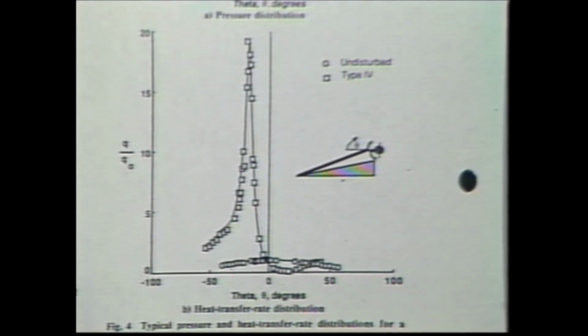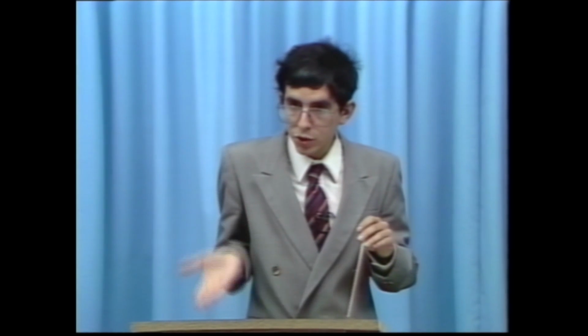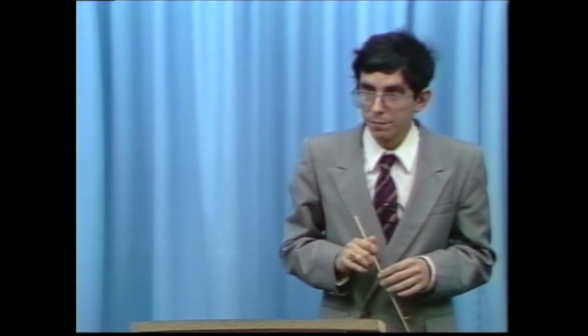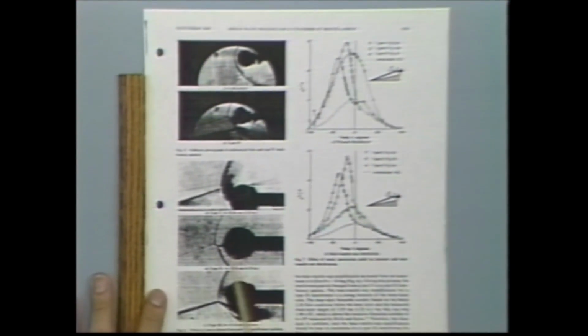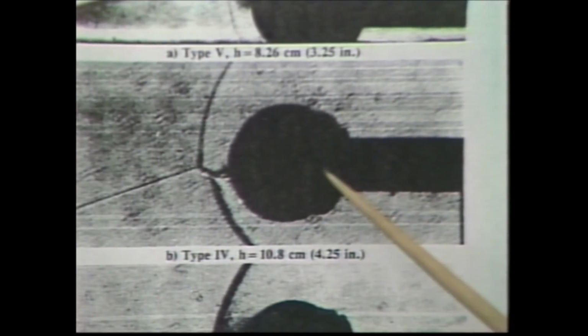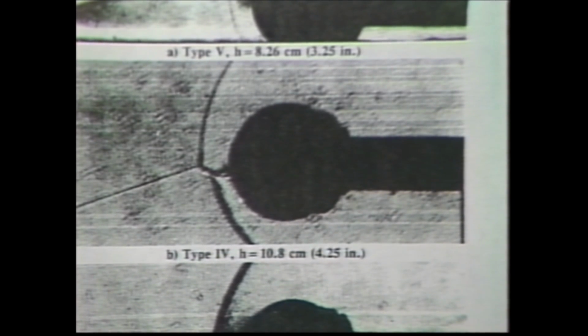So one of the goals in dealing with the shock on cowl problem is to try to make sure that the shock does not exactly touch the cowl. If that shock sweeps by the cowl, you really want to minimize the time during which that shock passes by the cowl. And here, let me show you some Schlieren pictures, again courtesy of Mike Holden. Let me call your attention, this is a Type 4 interaction. You can actually see the picture. This is a free jet impinging, I think this was a sphere in the cowl span tunnel. And it's quite a dramatic effect.